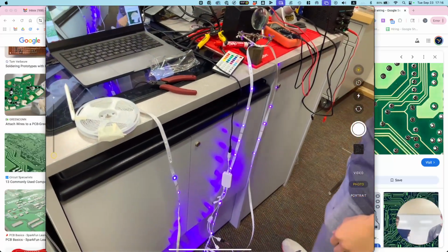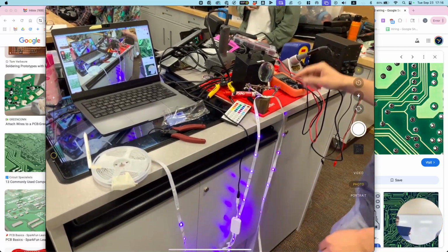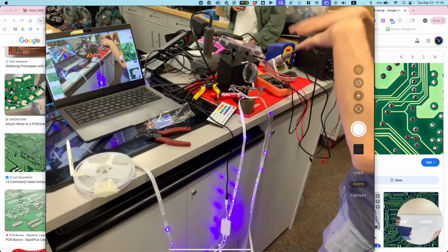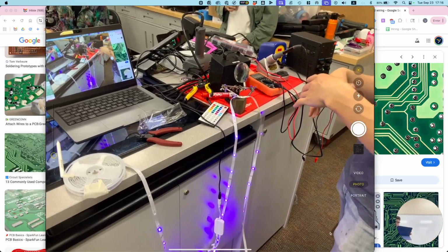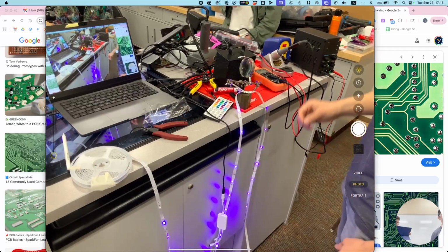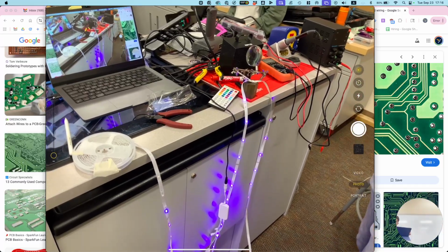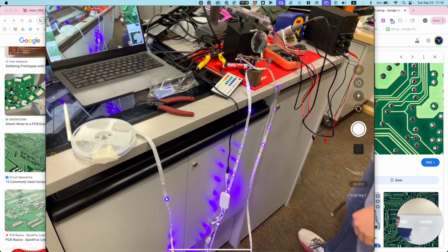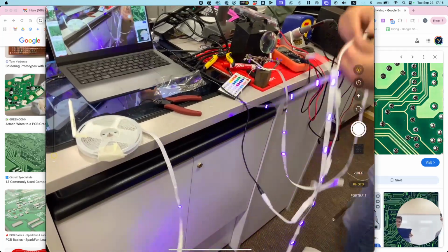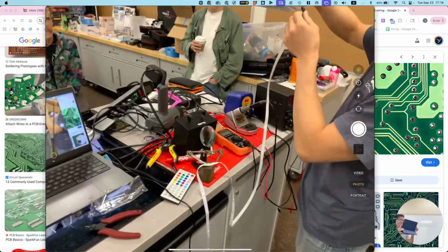This one right here. Okay, I was gonna say we might want to put some heat shrink, not because it needs to be electrically connected, but because this is kind of a weak joint right now. And I don't want it to break again. So what I might actually want to do is get a little piece of plastic. Shoot. See, this is an instance where I didn't put the heat shrink on. I should have done that earlier. But it's okay, because I can unplug from this end.